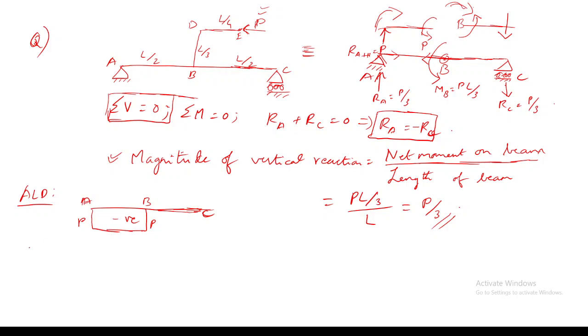And for the shear force diagram, can anyone say how it will look, whether it's positive or negative, or what the structure of the shear force diagram will be? It will be positive throughout. Why positive? Because it is in clockwise direction. So it will be P by 3, here also P by 3.